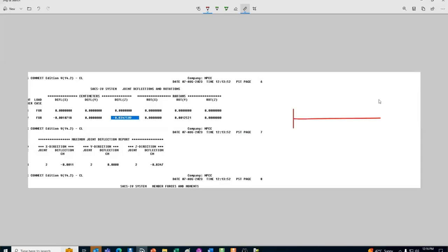You see here, if the force is applied here, the displacement would look like this. What is the value of this? Maximum displacement is P L cube divided by 3 EI, right? So if you substitute all these values, we know P is 10 kilonewton, L we also know, that's 10 meter. 3 we know, E is Young's modulus, we know, I, the section moment of inertia, that also we know. If you substitute it, we can get this value.